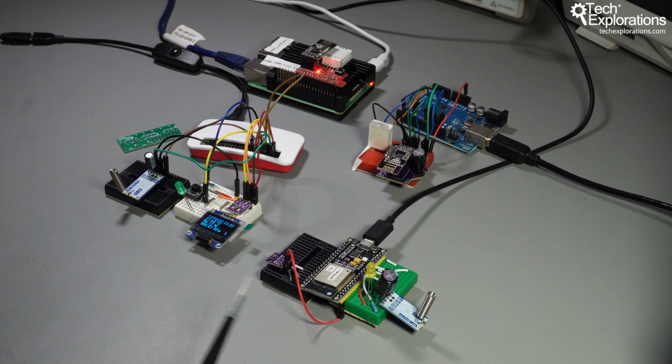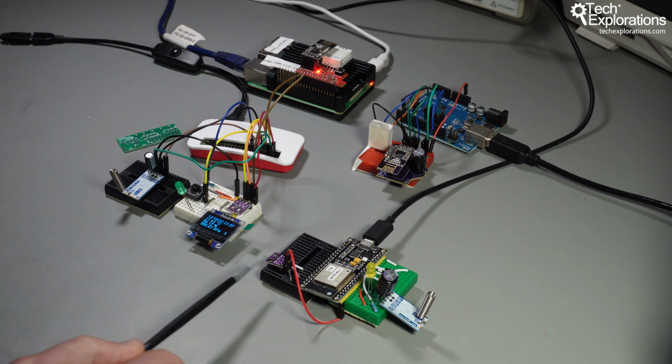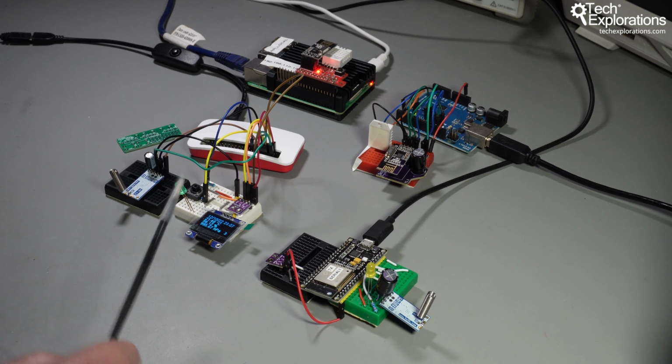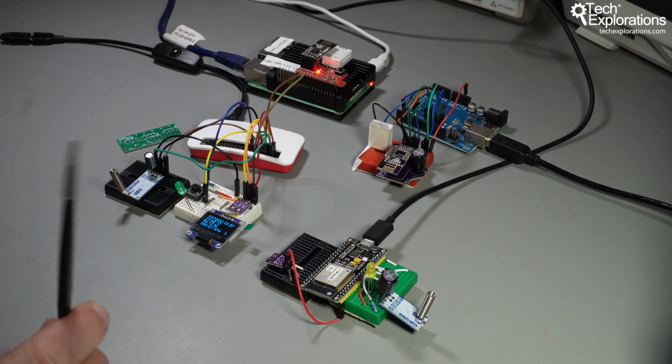It's just going to work as long as you've got a UART serial interface available for the HC12 transceiver and an I2C channel or interface for the sensor. Your remote node is going to work. But I thought I'd just use an ESP32 because I've got a lot of those modules, so I didn't have to go out looking for new devices to implement here.